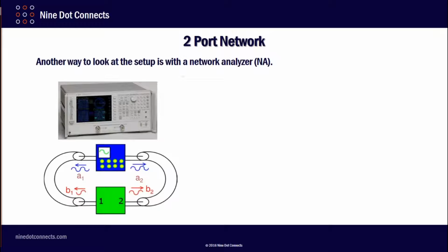Let me put it this way. When you first learn circuits, you don't necessarily think about the current as it relates to two different lines at one time in the circuit. You think about it leaving the one node on the source, going through a series of impedances, and coming back on another trace. Well, you've got to not look at the way high frequency circuits work like that. The positive and the negative are related to each other in physical space.